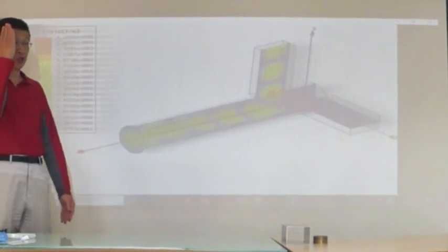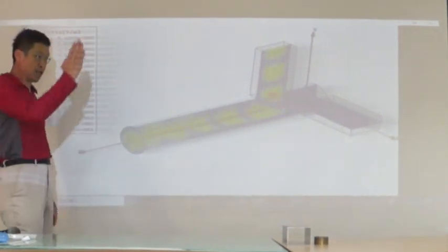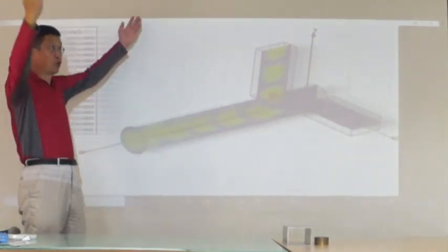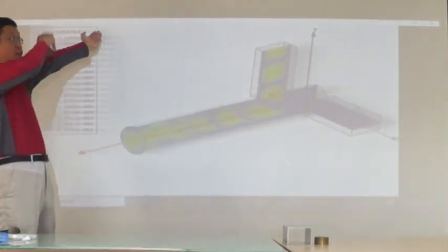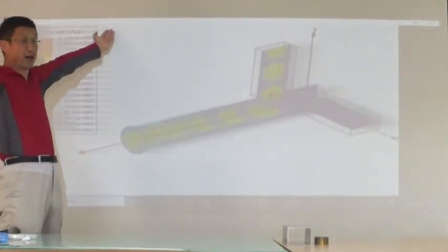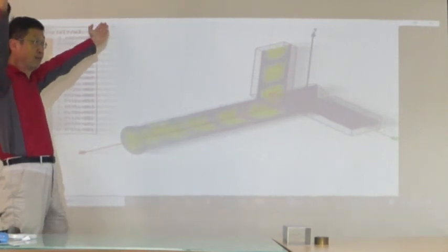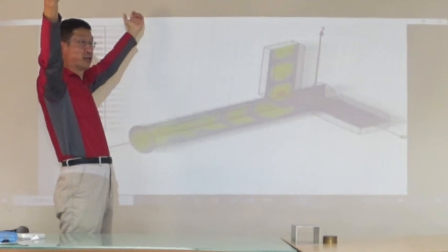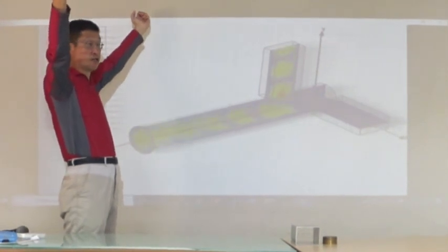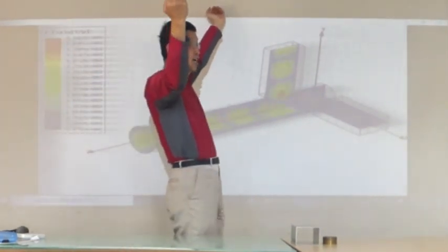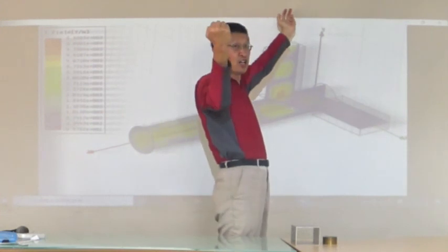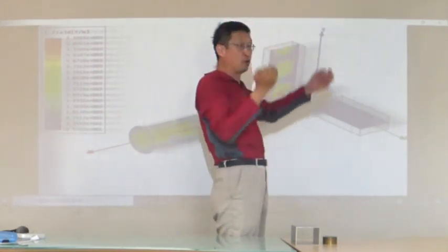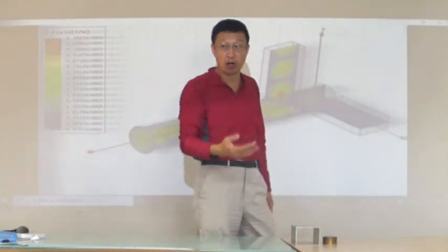Just imagine a linearly polarized wave, just like this one, is divided into two components, separated by 45 degrees. And then the propagation constant for this one or this one is slightly different. So one travels faster, the other is slower. And eventually, something looks like this one is largest, this one is smallest. So it looks like circularly polarized.